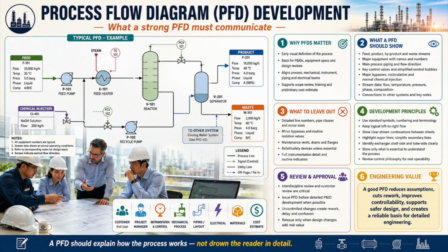Equipment capacities, dimensions, design pressures, metallurgy, and nozzle data are normally controlled through equipment data sheets and specifications. Equipment titles should be concise, descriptive, and based on agreed project terminology. Place equipment titles and numbers along the top of the drawing, aligned vertically with the relevant equipment wherever practical. Rotating equipment may be shown along the bottom when this improves readability.